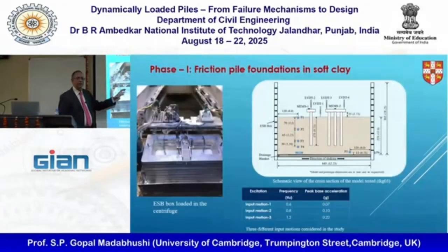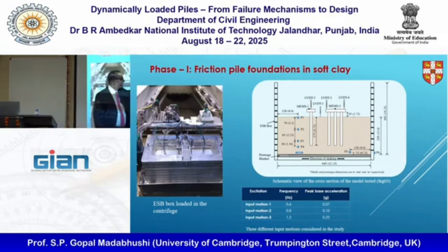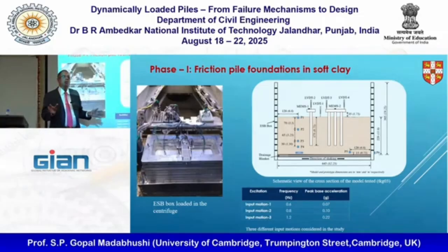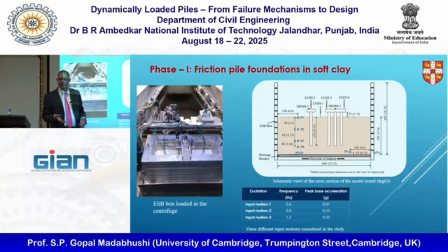Again, I'll do the centrifuge modeling part tomorrow. I can't do everything at the same time. But you can see he created a soft clay and installed these piles, and everything is in clay. So these are what you would call floating piles, piles which are not actually going into the sand. And he tried different earthquakes.